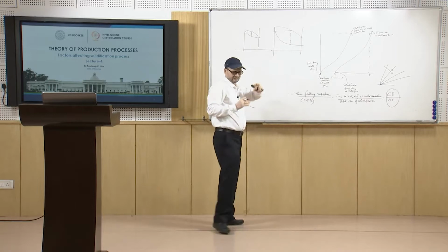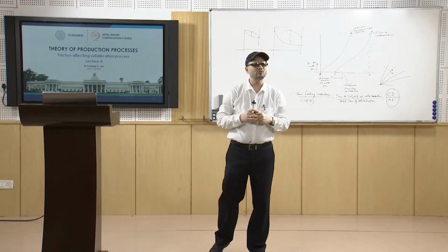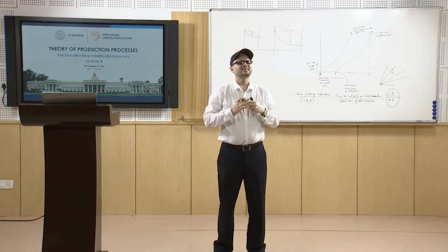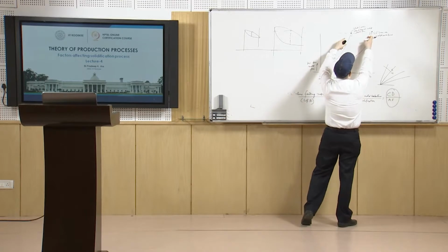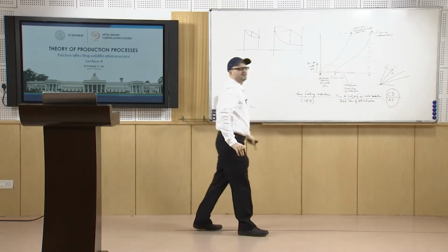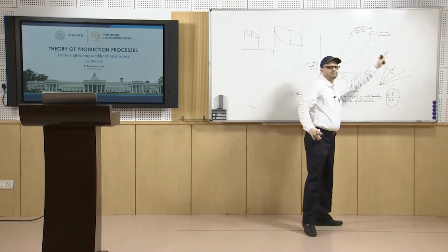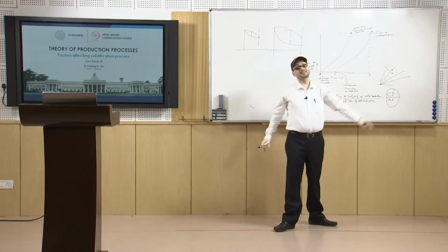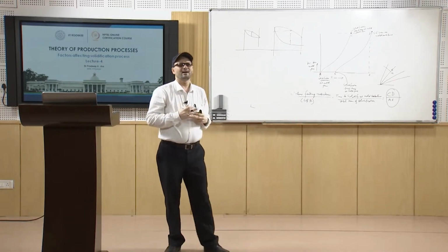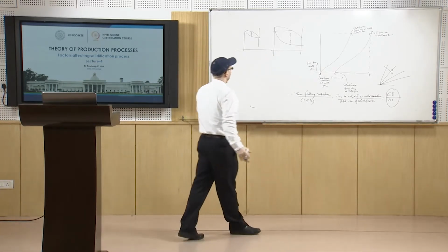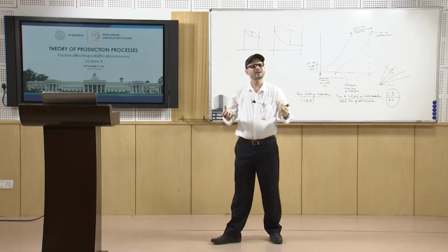So, if the solidification range of the alloy is more, the CFR value will be more, and that will increase this width, the gap, I mean the time required to solidify at the center line, and if it is more, the CFR value will be more, and then there will be chances of defects, and the alloy will be difficult to be fed.